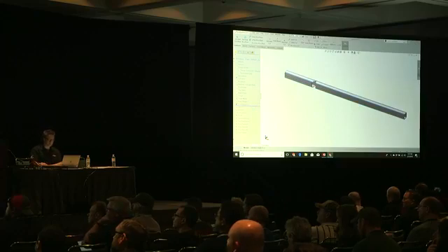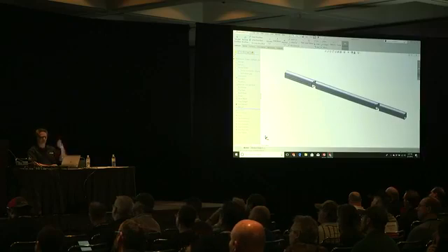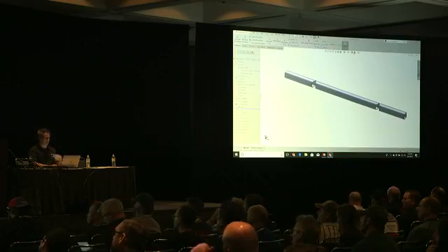So put my cut in, I mirror it. Just so you know, in case you didn't, feature manager tree, once you move the rollback bar, there's a setting in your tools options. You can arrow key up and down through it. I like to do it when I'm checking out what somebody's done with a part, just to see how they built it. So made a cut, mirrored it.